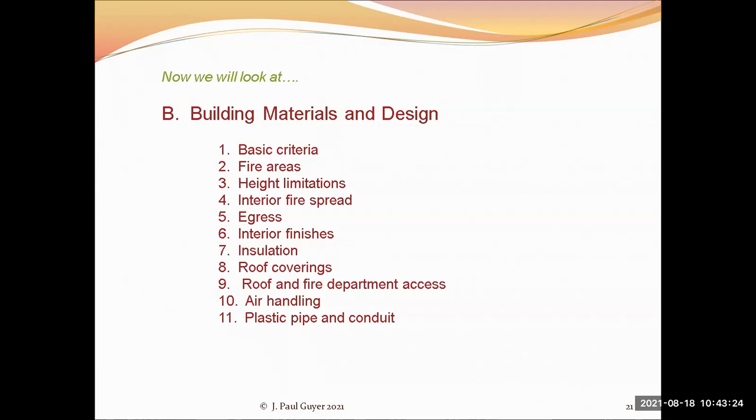And so these parapet roof requirements in the codes will be more stringent when your buildings are close together. Also, the closer together your buildings are, the greater the codes will require fire resistive construction. Again, that's kind of why, if you have multi-story buildings, for instance, typically the walls that are adjacent to other buildings are of a highly fire resistive type of construction, like poured in place concrete, things like that.